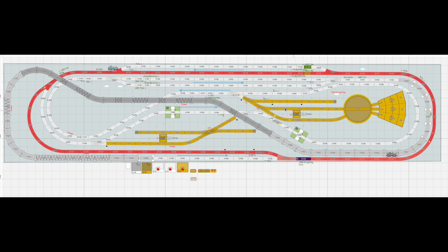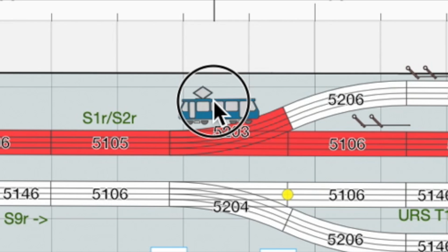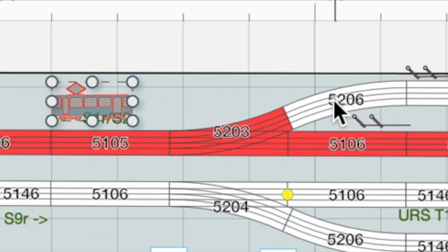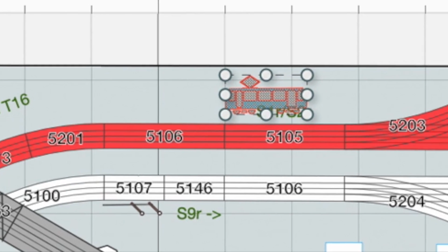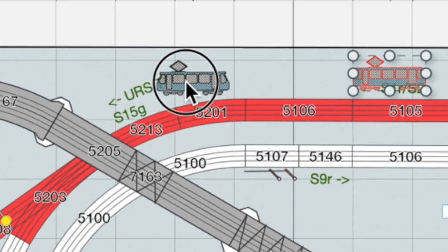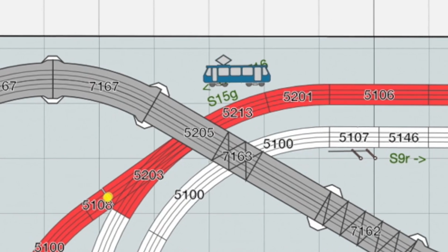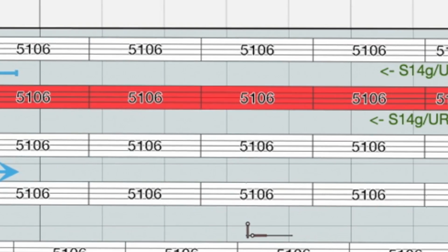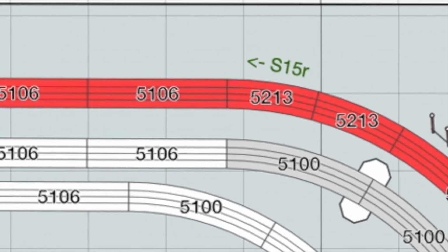The other train will get on its way, and the train exiting the station will first set the signal behind it back to red, then carry on its journey to hit a second switching track, which will set the signal before the station to green.